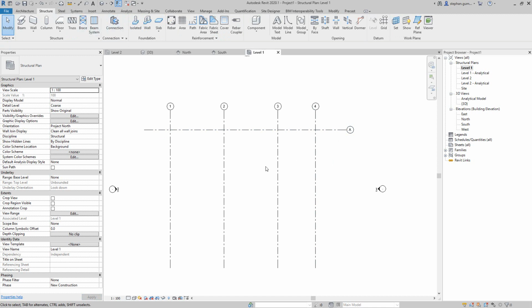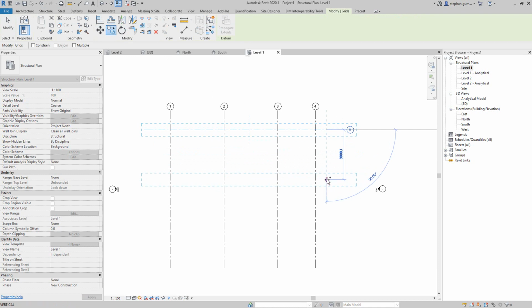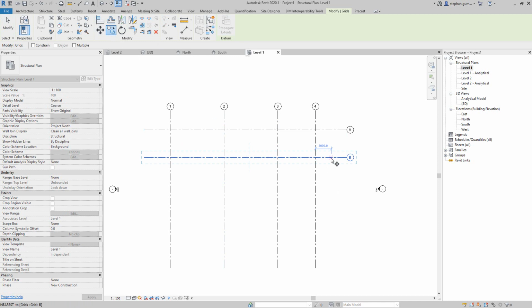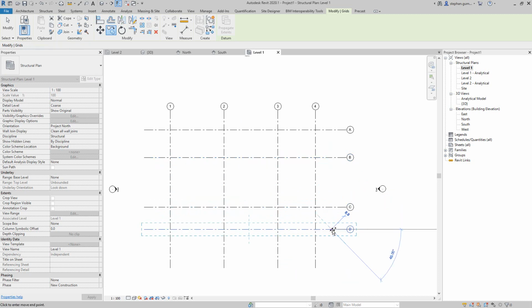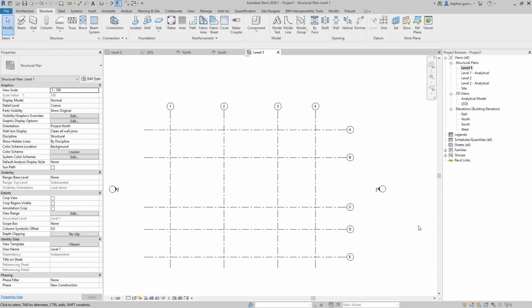So now if I come in and choose to copy that down, just like AutoCAD, I can type in here, go 5 meters. You can see it's come down 5, and I've now got a grid B. And of course, we can do this all day long. And if I want to do multiple, I just check the option up here, come into here, choose 9 meters, then maybe 4 meters, and then 5, and then we hit cancel and cancel, and you'll notice that I have my grids.